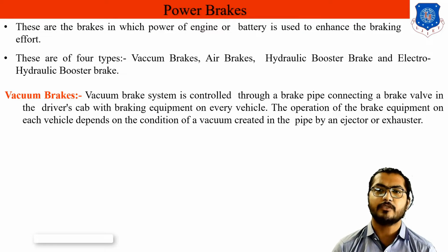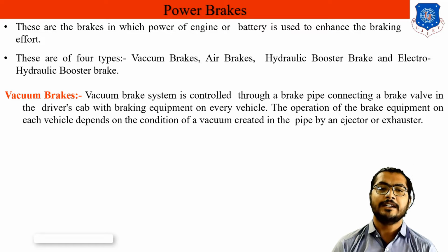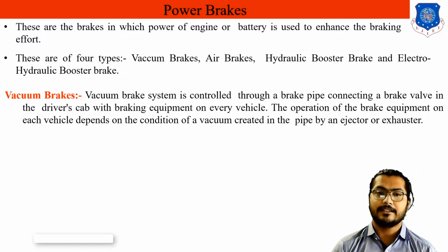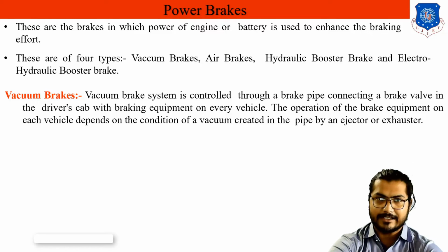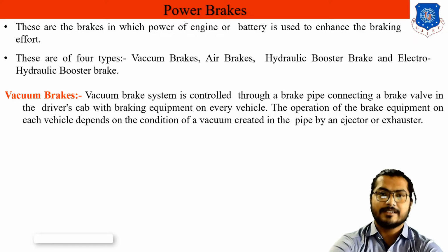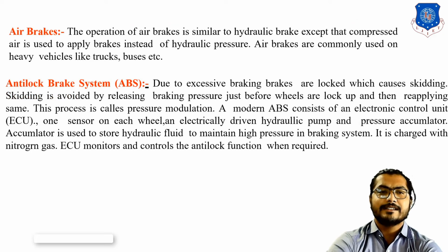Okay, the operation of the brake equipment on each vehicle depends on the condition of vacuum created in the pipe. That means it depends on how much vacuum there is, that is, pressure inside below the atmospheric. The vacuum is created in the pipe by injectors or exhausters. So in that case, injectors or ejectors or exhausters are used to create the vacuum, and this is called a vacuum braking system.